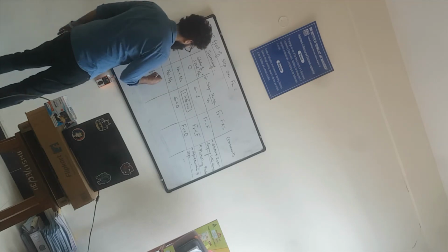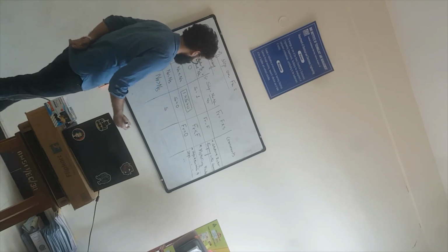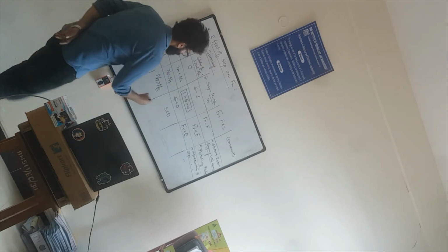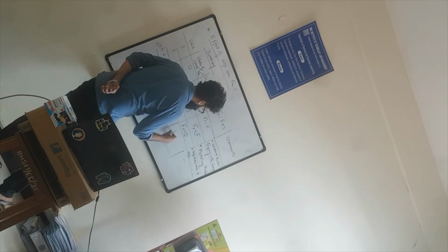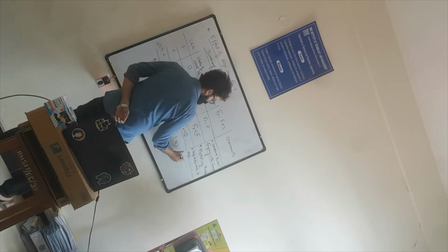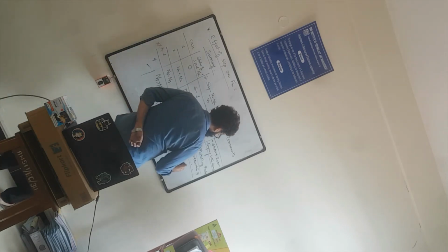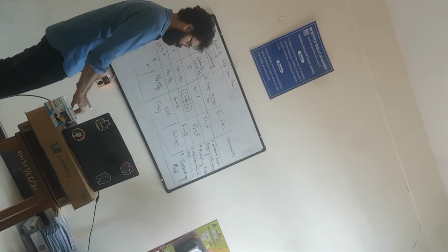Okay. So that's right. Finally, you have NR greater than NS. If NR is greater than NS, then slip is less than 0, or negative. When slip is negative, Fr is negative. What is the indication? The indication is that the machine is operating in generating mode.